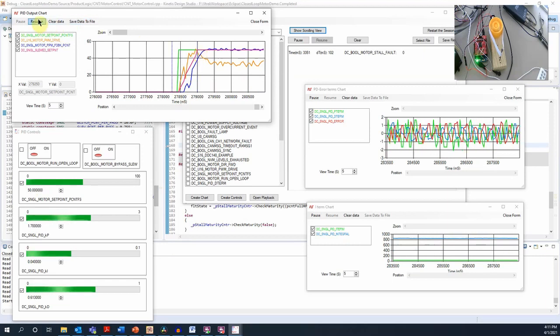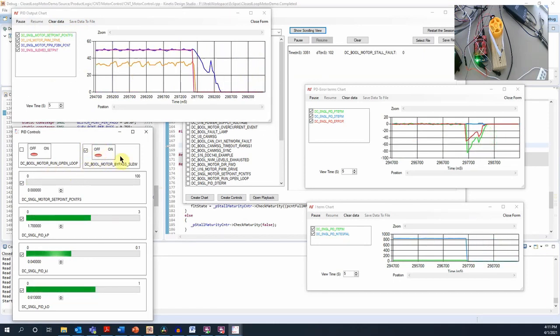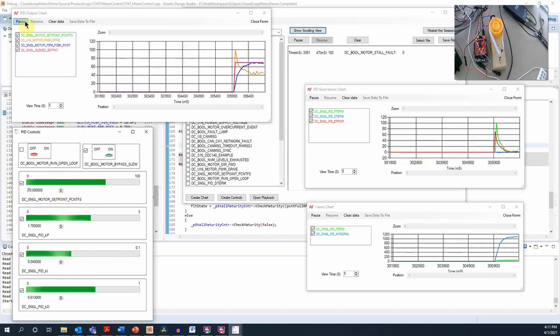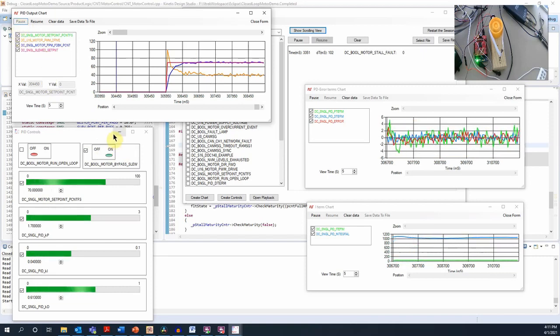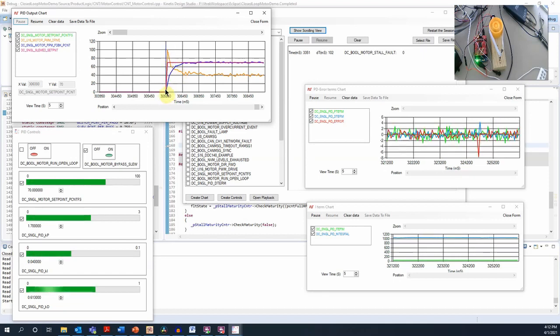And so now I want to show you what happens if we don't have that slew function in there. I'm going to go to 0 and then enable this slew bypass and turn it on. And then I'm going to go to 70%. We should be able to see what I'm talking about. In this case, power went up to 100%, so it hit the ceiling. We didn't have any headroom left, and that was when we went from 0 to 70%. So for a short period of time, we were maxed out, and we really didn't have any control over what happens